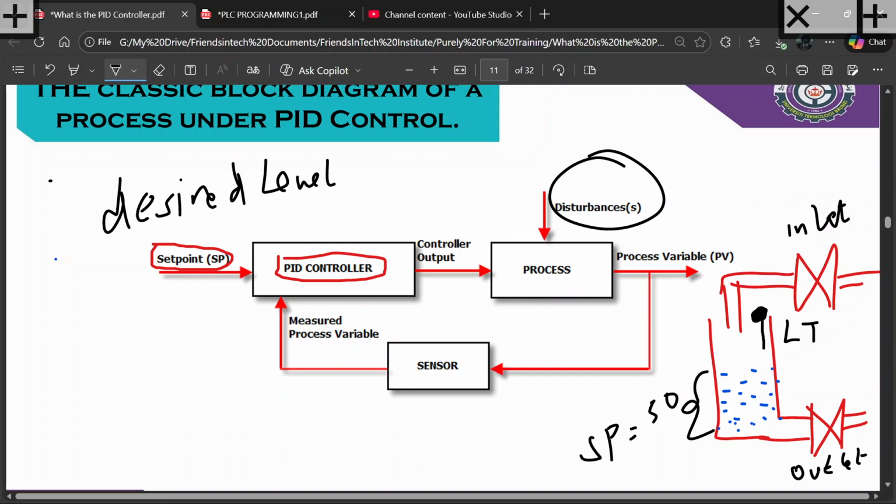So you get controllable signal, then you take this to actuator. You know you have an actuator there, then to the process. So finally the output from the process, what is called the process variable, PV, very important, PV. So here we are just checking the actual level using an LT. So this sensor here is level transmitter. Then we get to compare that here.